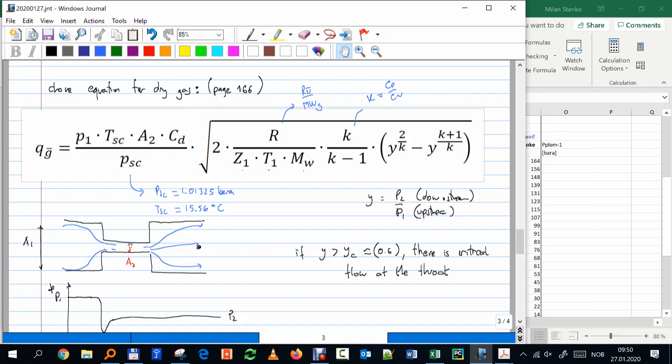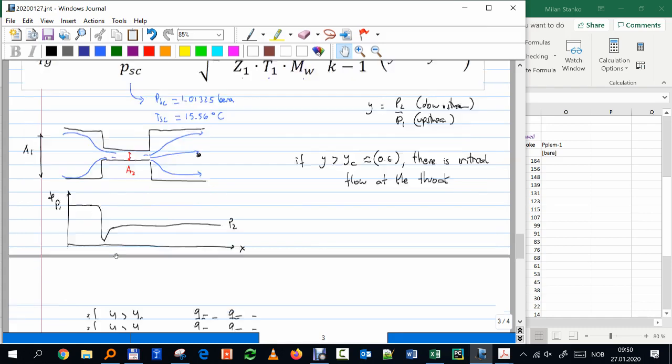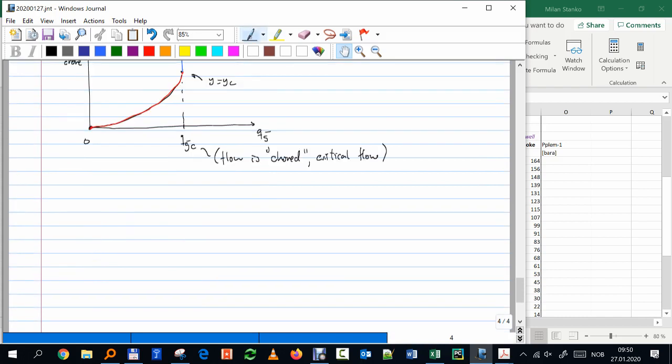A2, this throat, actually. I can change that by putting in a smaller choke. That's what I do onshore: I unscrew the choke and put in another insert with a smaller or bigger throat, which I call in 1/64 of an inch. So in onshore fields, let's make that comment.